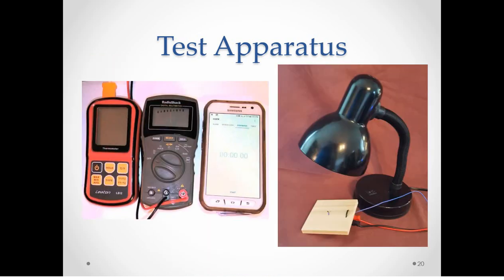In this slide, you're shown the two parts of the test apparatus. In the photo on the left are the three instruments that will be used to take the experimental measurements. The thermocouple lead was connected to the digital thermometer. When the thermometer is turned on, I will verify that the temperature is measured in degrees C and that a type K thermocouple was selected.